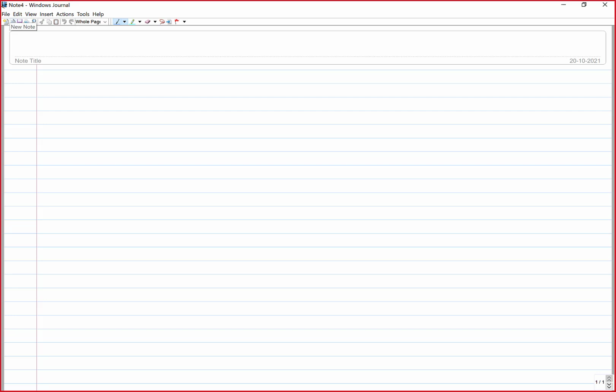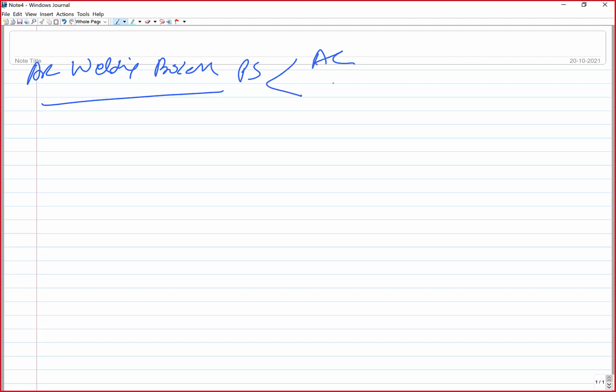Okay, that was about the consumable electrodes and the consumption rate or deposition rate. As far as welding processes are concerned, arc welding processes especially use two types of power sources, AC and DC. DC is preferred in a number of situations where you have the choice of heat generation as per your need, and your arc stability is also good when DC is used.